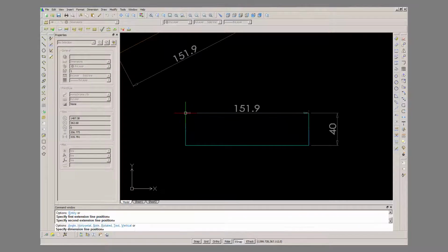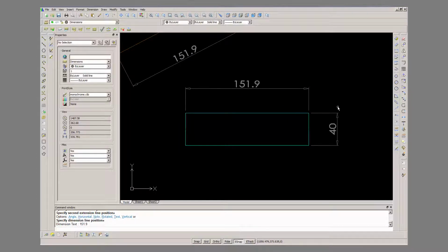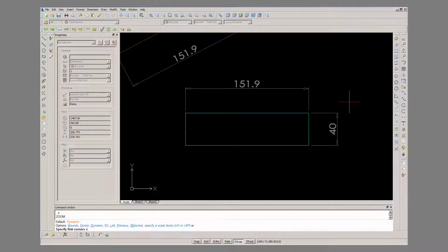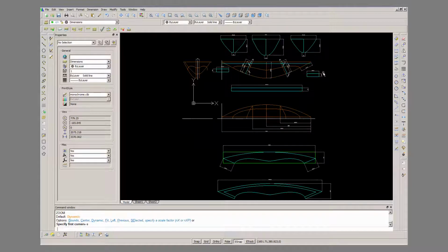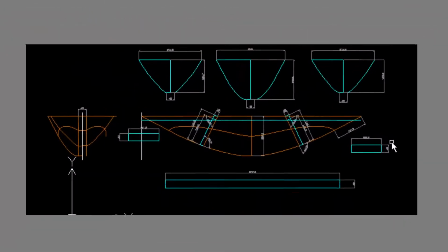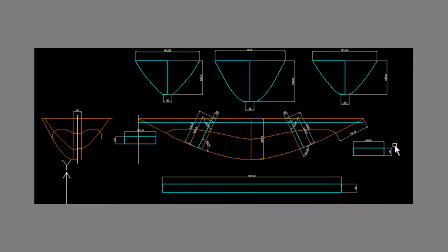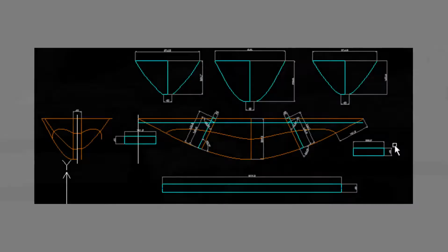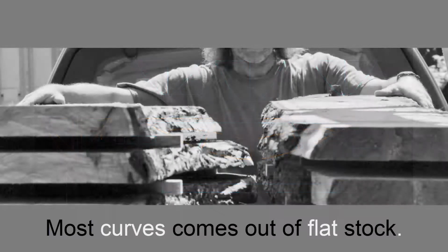This, what I'm doing now, is the last dimension that I add to this drawing, which is actually nothing else than the flattening out of the drawing you saw here before, the three-dimensional drawing. I need that to get my measurements, and you have to realize that everything comes out of a flat sheet or a flat blank, and that's why I need this translation.